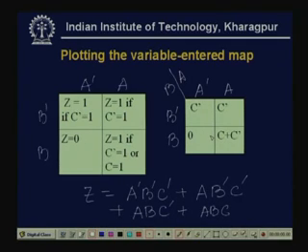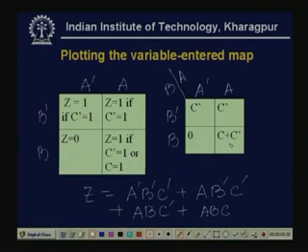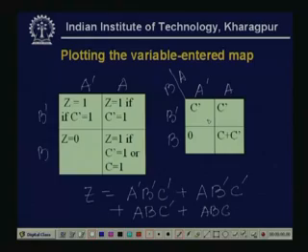So, in the normal K map these were actually either 0 or 1. If the min term exists, then that particular element we put as a 1, otherwise it is 0. Now, that 1 is replaced by the third variable, which I have not considered in my map. See, actually there are 3 variables A, B, C. I have considered only A and B as the map variables, and C as if C or C complement or some combination of C, that means C or C dash.